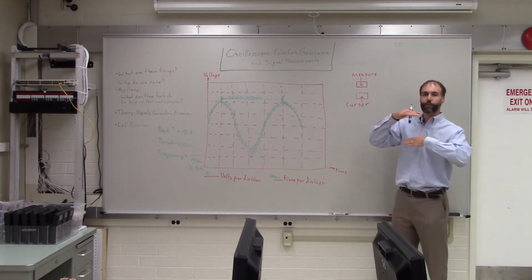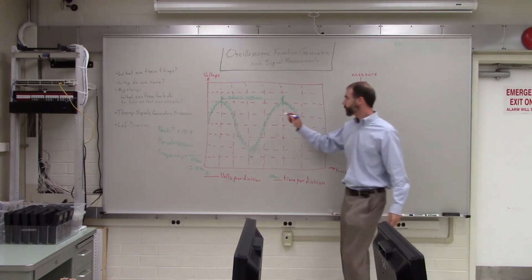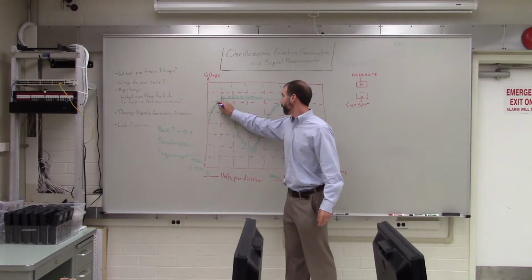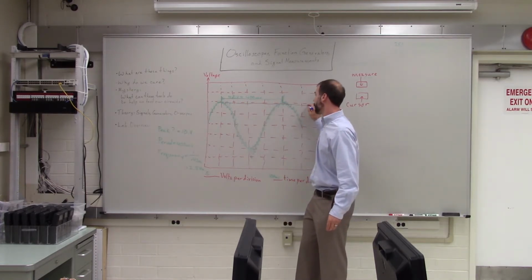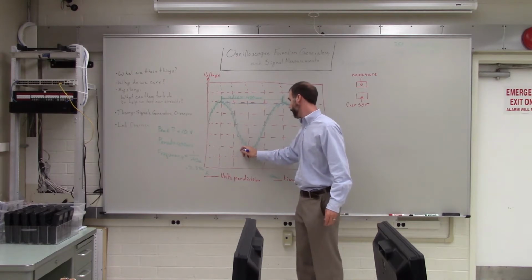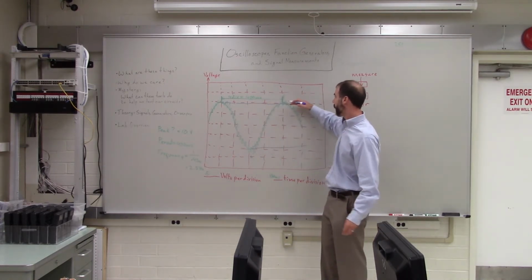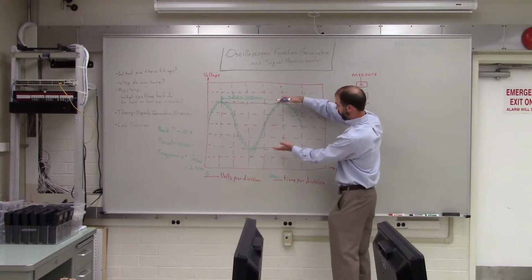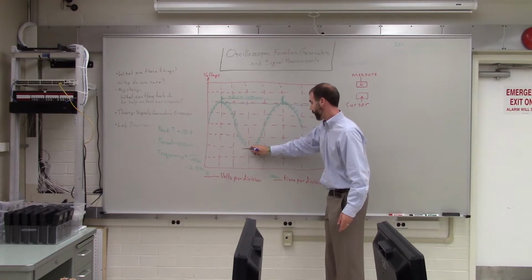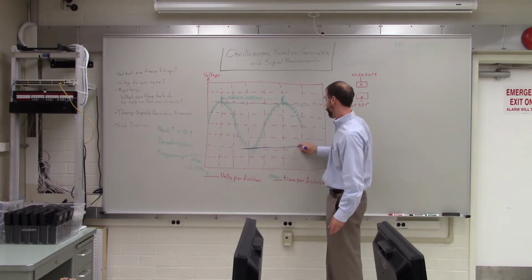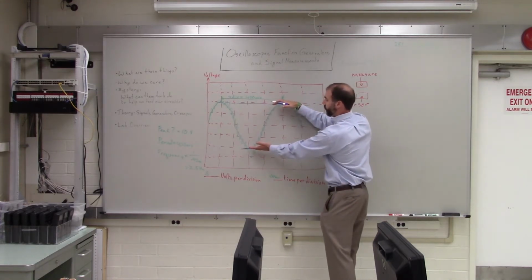So you can either have vertical lines or horizontal lines. So you can set these cursors to various points that are interesting to you. So if you had a noisy signal like this and you wanted to measure from there to there, you could use cursors and move them until they were at the spot where you think is the top of the signal and the bottom of the signal.